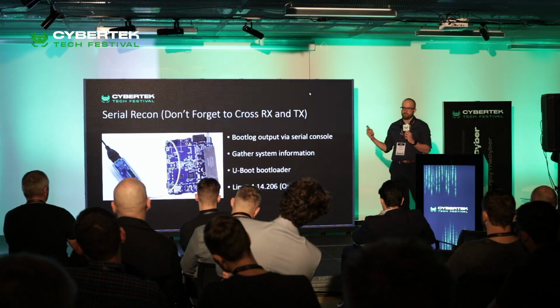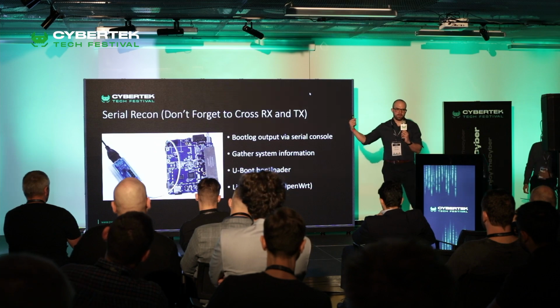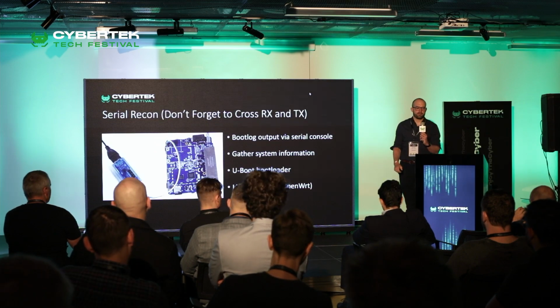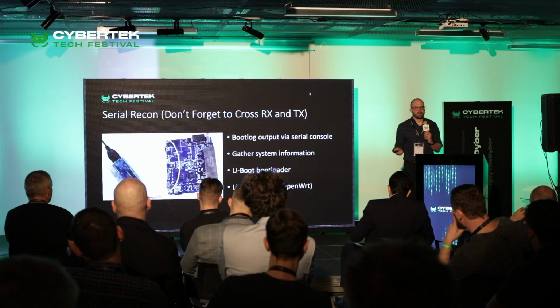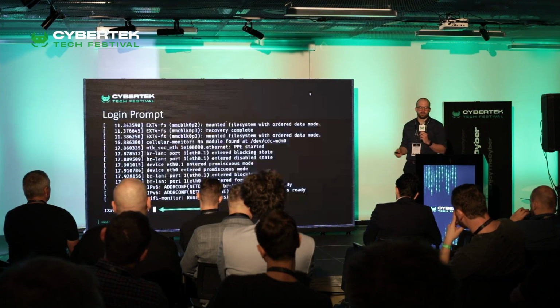When we connect the USB UART interface, we must cross RX and TX, because in one device the transmission channel must end up on the receiving channel of the target device. We immediately learn that the system is running on the U-boot bootloader and is running on OpenWRT, a specialized Linux image for switches, routers, edge devices, and so on.